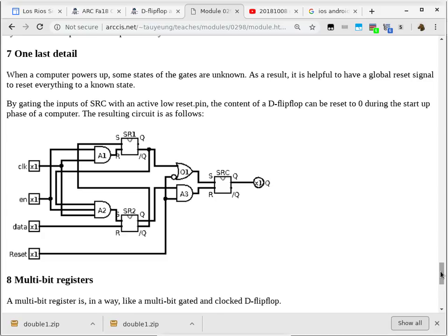It's a timer. So it's going to go off and say, something bad has just happened. And that signal goes into what we call an NMI line of the main processor. NMI stands for non-maskable interrupt. It cannot be stopped. It goes into the processor. And then the processor goes into panic mode and says, holy beep, something bad just happened. Something really, really bad happened.